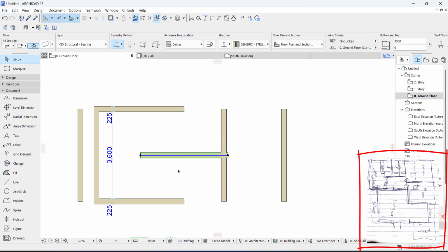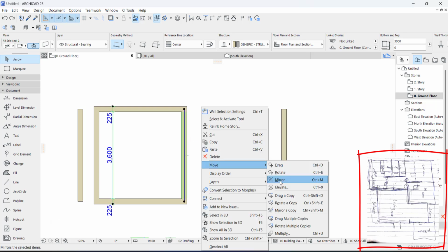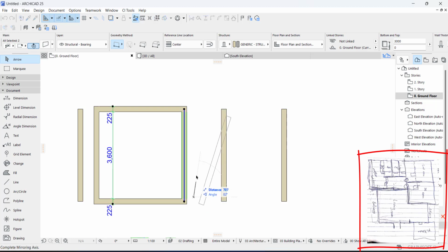It could be a chair, anything, right? It will rotate it. If you also want to mirror, you can easily just click mirror and click this place, and you get it. So that's how to move, rotate, and do all these types of things with Archicad. I've not deviated from drawing the plan yet. I'm just showing you something you need to know using Archicad.